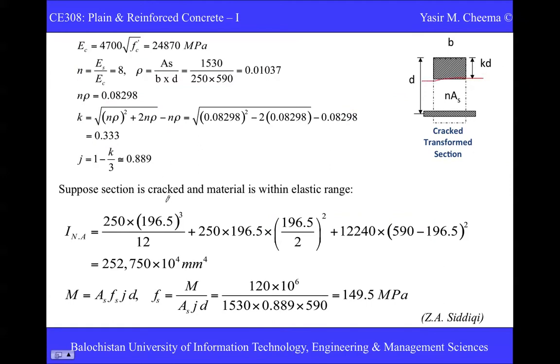Now we're trying to find the moment of inertia at the neutral axis. As you remember, I told you about the moment of inertia. So this is first bh cubed. This is our one section, this uncracked section 1. We are just trying to find the moment of inertia of this uncracked section about this neutral axis. See here the cursor, this is the neutral axis.